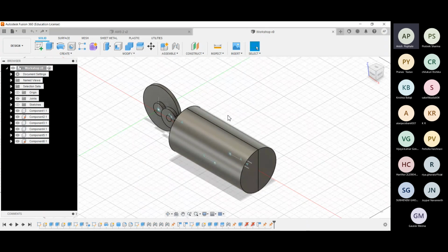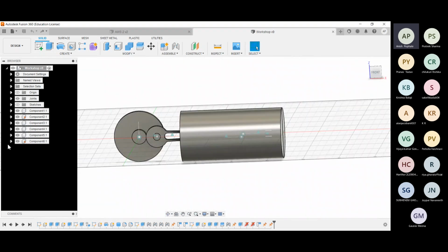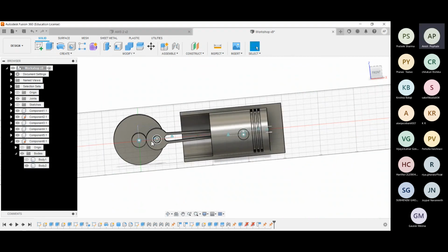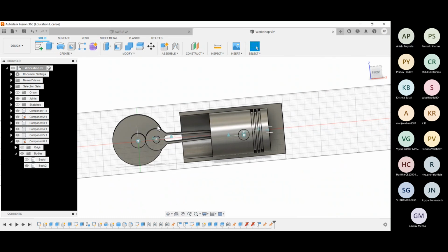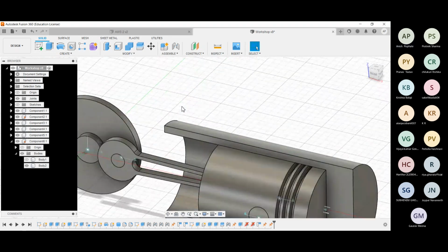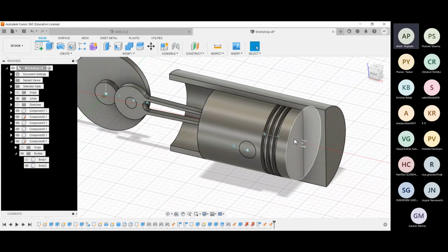So first we have this, just to explain more about joints. So this mechanism here is called a crank slider mechanism. Basically, it converts a rotatory motion of this disc into a linear motion of this piston. So here also we have different kinds of joints. In this model, this is the symbol for a revolute joint, and this is a sliding joint.